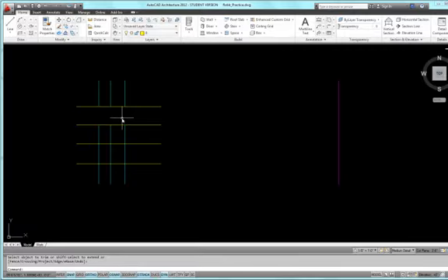Now let's review this again. TR Enter. Pick a cutting plane. This time we'll use the 2 cyan lines as our cutting plane. Hit Enter to go to the next step. The command line now indicates that we need to select an object to trim. And Enter ends the command. Okay, so now that's the way that you use other objects as cutting planes in Trim.